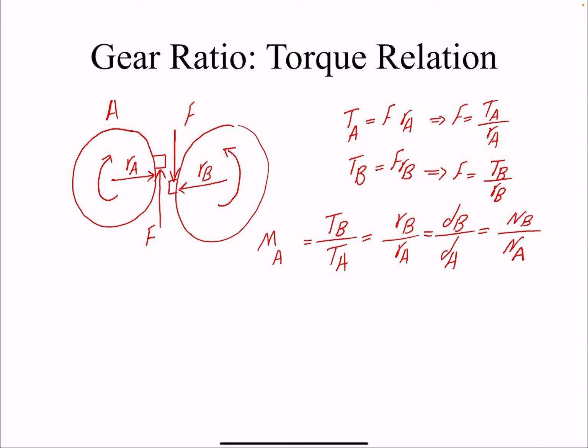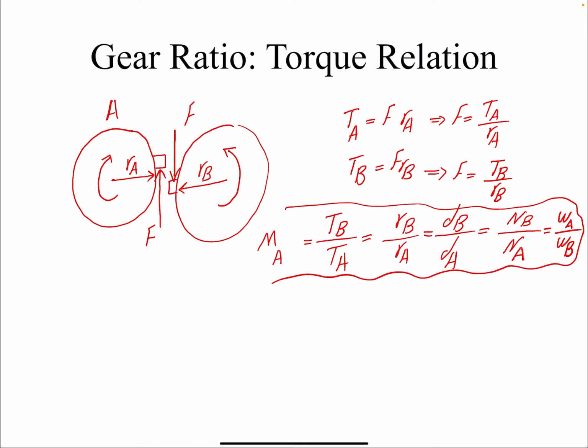If you have an electric motor or an engine, for example a manual transmission, you have reductions. You're increasing the torque for gear 1, gear 2, gear 3, gear 4 is directly connected, the input and output, and in gear 5 you're kind of increasing the speed. But in most cases, you have reduction. So this is a mechanical advantage. If I write my speed ratio, which was the only one that was inversely proportional, I get this long ratio.